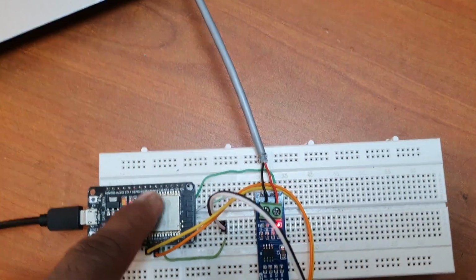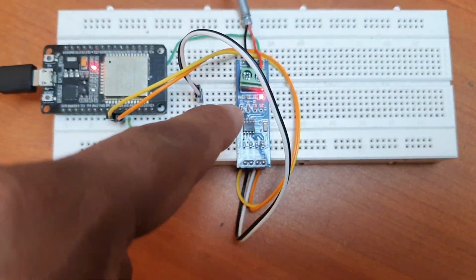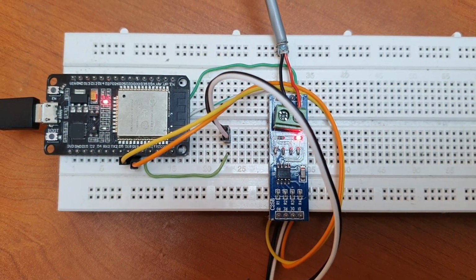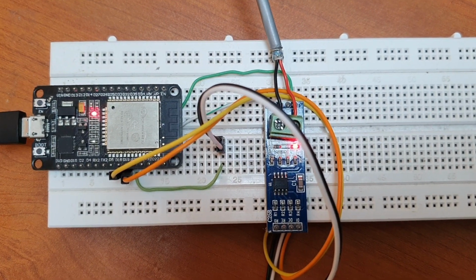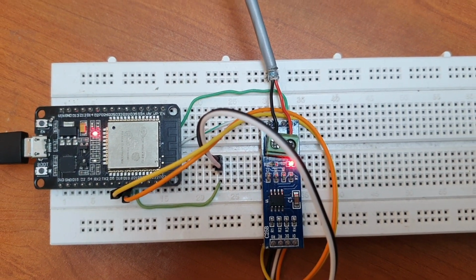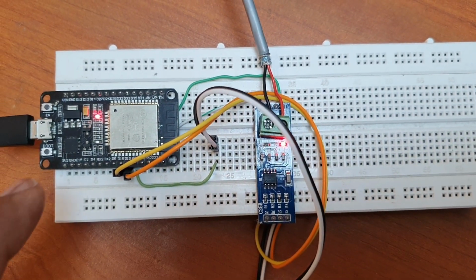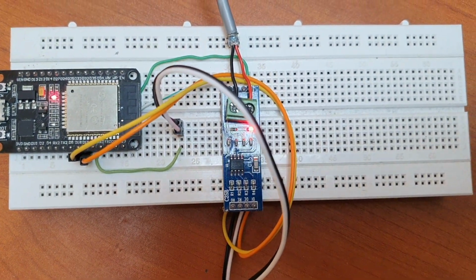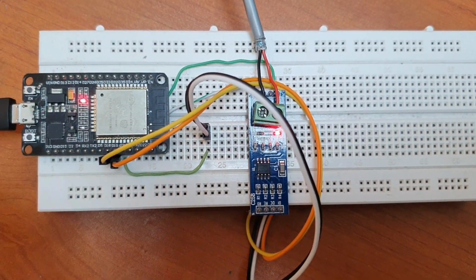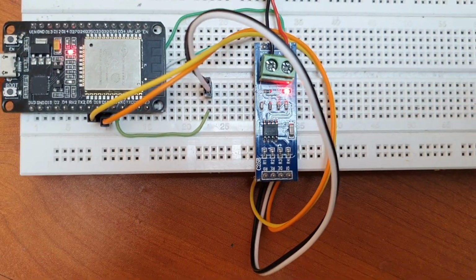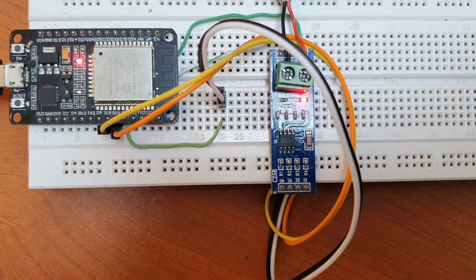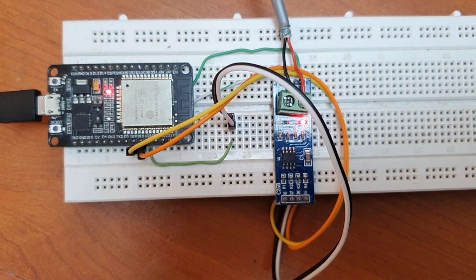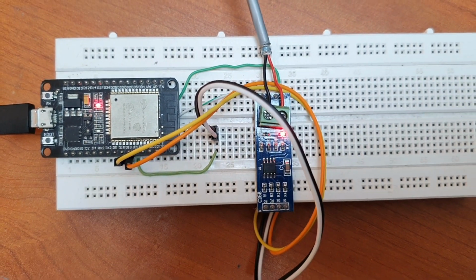And this is a standard ESP32 demonstration board, and this is the RS485 transceiver. The transceiver has mainly two ports called RO and DI. RO is the receiver output which is connected to pin number 18 of the ESP32, and the DI, driver input, is connected to 19 of the ESP32, and there are another two terminals called DE and RE, driver enable and receiver enable, and both are connected to pin number 21.